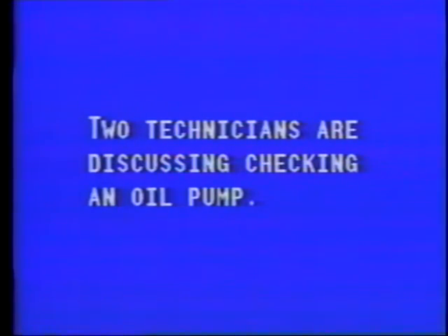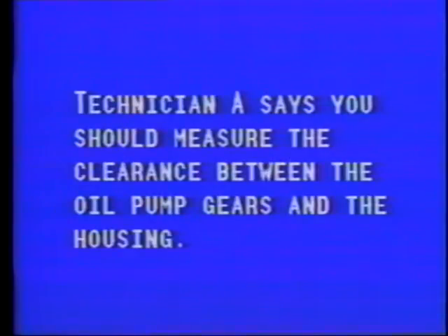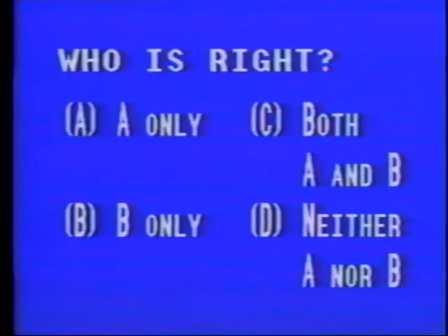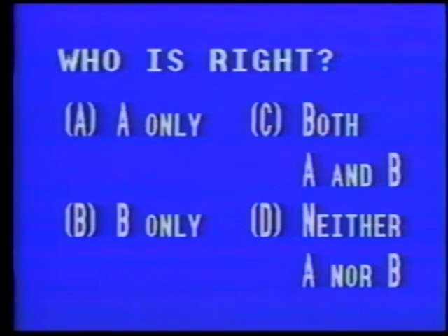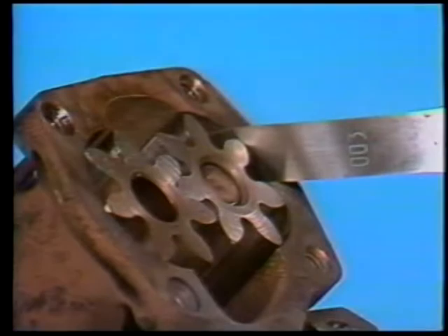Two technicians are discussing checking an oil pump. Technician A says you should measure the clearance between the oil pump gears and the housing. Technician B says you should measure the clearance between the oil pump gears and the pump cover. Who's right? A, A only, B, B only, C, both A and B, D, neither A nor B.